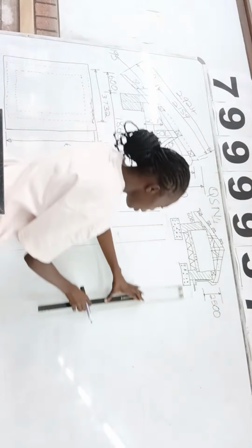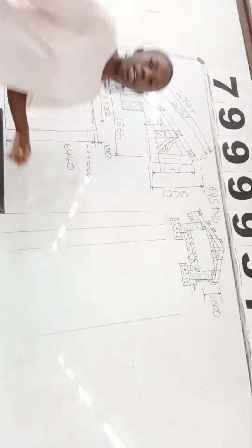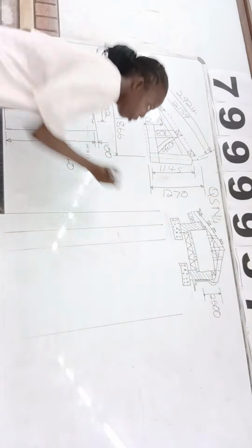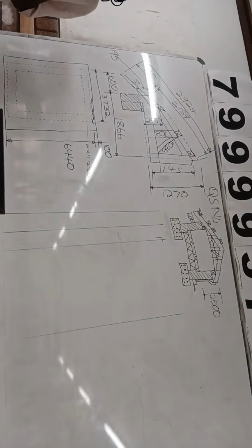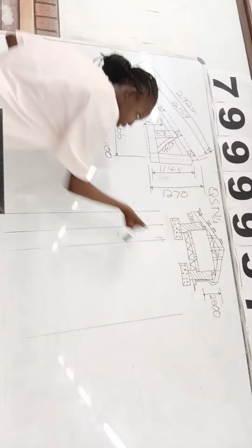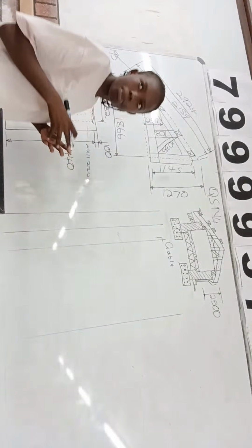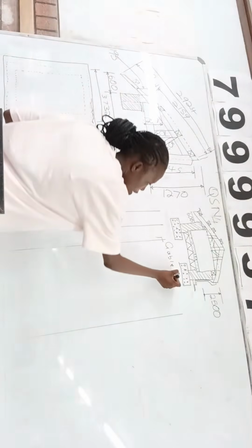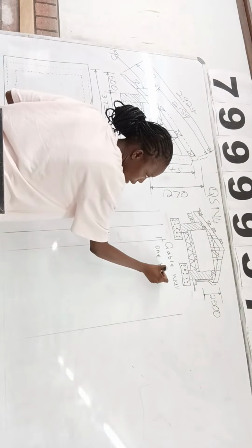Then a bigger one, like that. So you're going to open a bracket here. When you open your bracket, I'm not going to be writing full descriptions. You will check from past papers, but if it's a gable wall, this is the description. So this is a gable wall, and then here, method 1 brick wall.